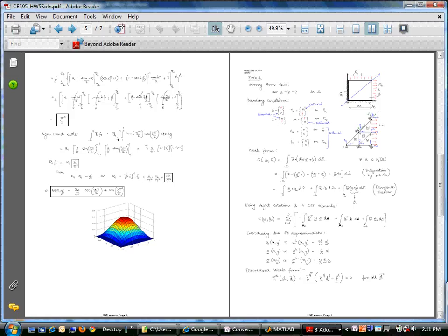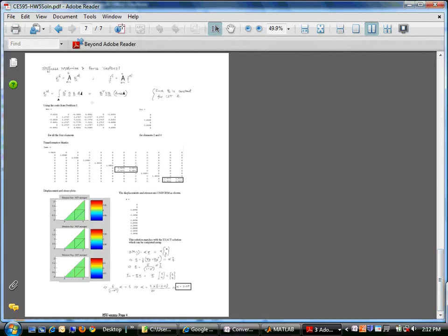Substitute your finite element approximation, and you should also be able to see that all the 4 stiffness matrices for all these 4 elements would turn out to be the exact same stiffness matrix.